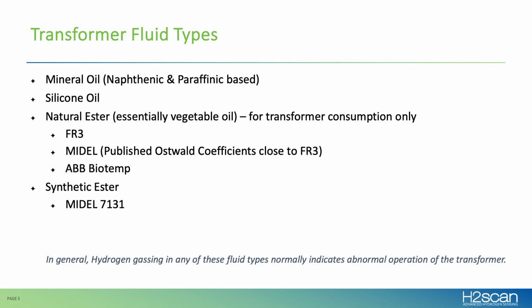But in general, many of the sensors in the market work with all these various fluids, but some do not. So if you're using a specific online monitor and you're going to start putting a different fluid in your transformer, you want to make sure that that online monitor is compatible with that fluid, because a lot of monitors out there are not compatible with the ester fluids.